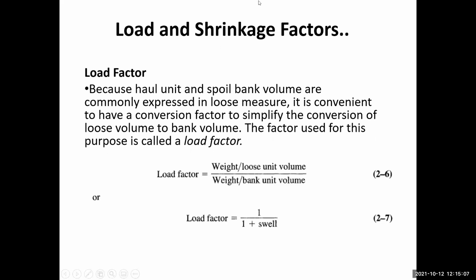Because haul unit and spoil bank volumes are commonly expressed in loose measures, it is convenient to have a conversion factor to simplify the conversion of loose volume to bank volume. So the factor used for this purpose is called the load factor.